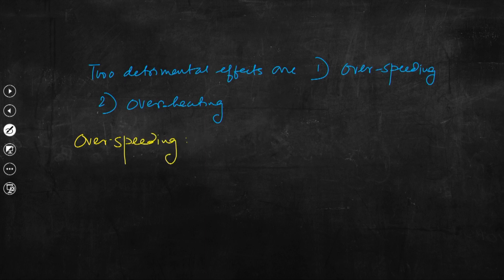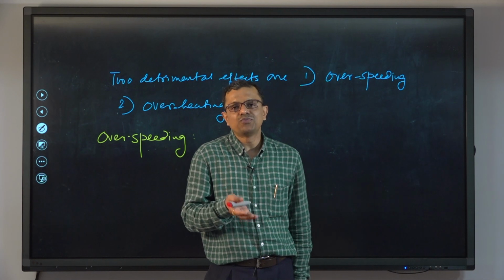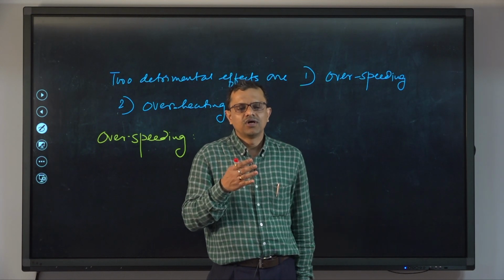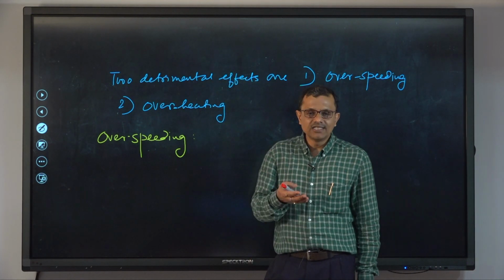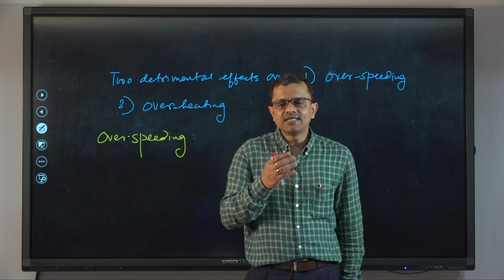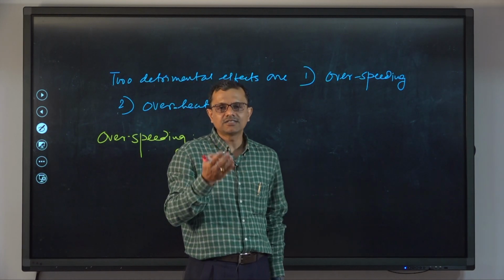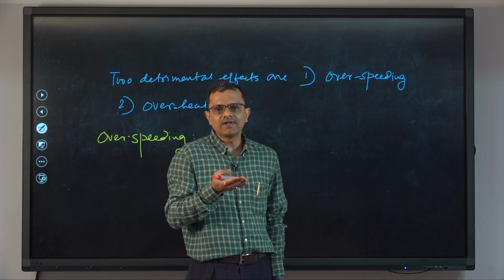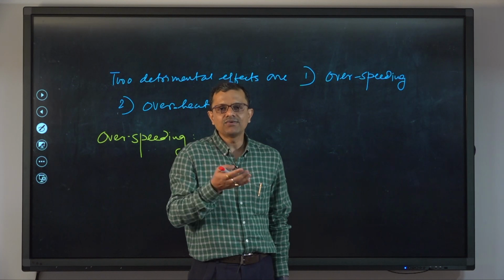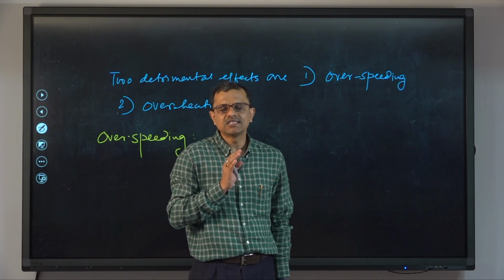You can understand that when the turbine and compressor are rotating at high speed to boost the pressure, and when these components are in touch with high pressure, high temperature exhaust gas, in particular the turbine, this is the fixed geometry turbine. When the turbine runner is rotating at high speed and the turbine blades are in touch with high pressure, high temperature exhaust gases, that condition may destroy the revolving components of the turbocharger or turbine. This is detrimental and is known as overspeeding.